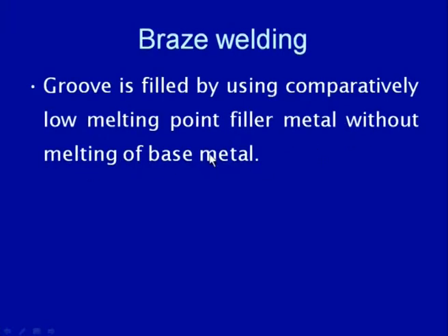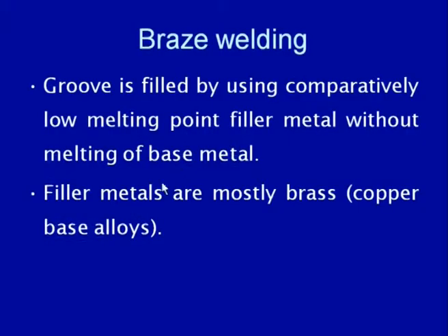So, our target is not to melt the base material, but only the filler material is brought to the molten state, and the melting point of the filler material is always lower than the base material, so that the groove can be filled in by the heat which has been supplied to the base material. The filler materials are mostly brass, that is the copper base alloys.